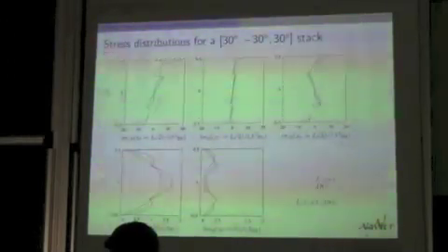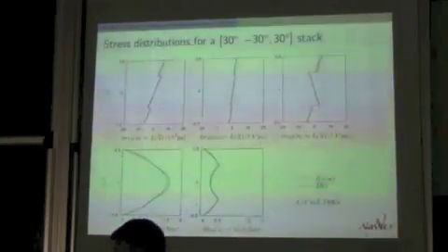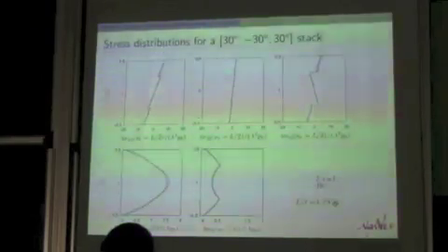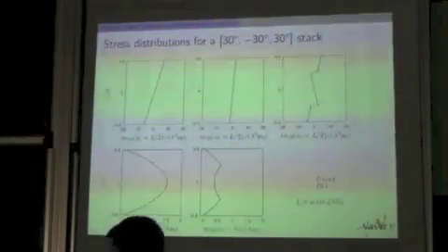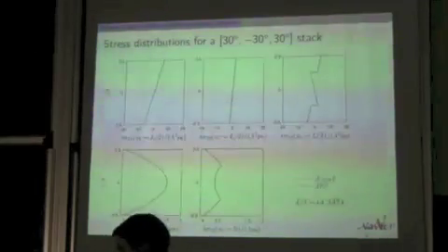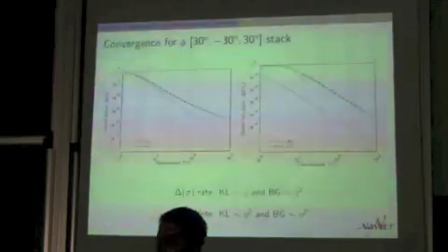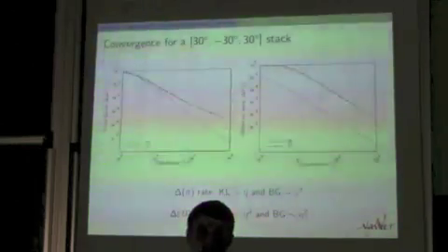Now if I increase the slenderness, you can see the fast convergence, look, we are just at 4. And for an engineer, at 10 I'm happy. Okay? So this is just an illustration of the stress state of the plate. And we can check this more precisely in terms of convergence diagrams.